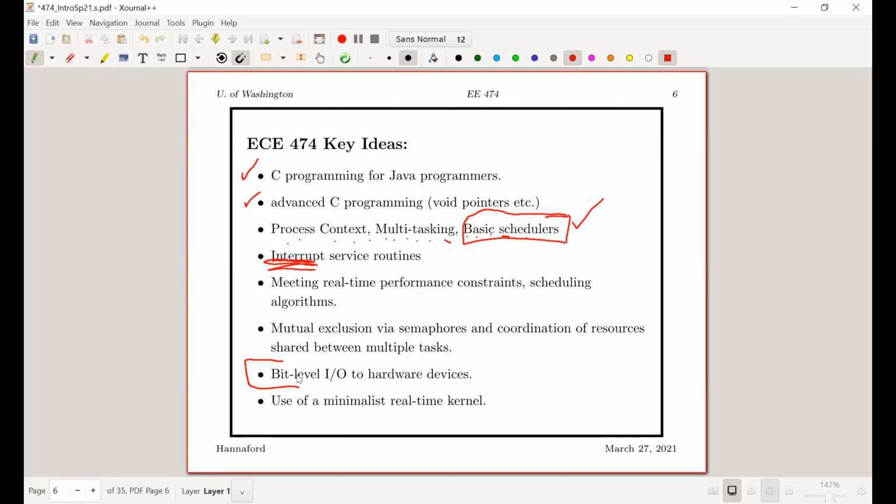But how does it work? What we're going to understand is, from the hardware description of the specific IO ports on this chip, how can we specifically control an individual bit? This is the information that the original programmers needed to know to write the function digitalWrite in the first place.